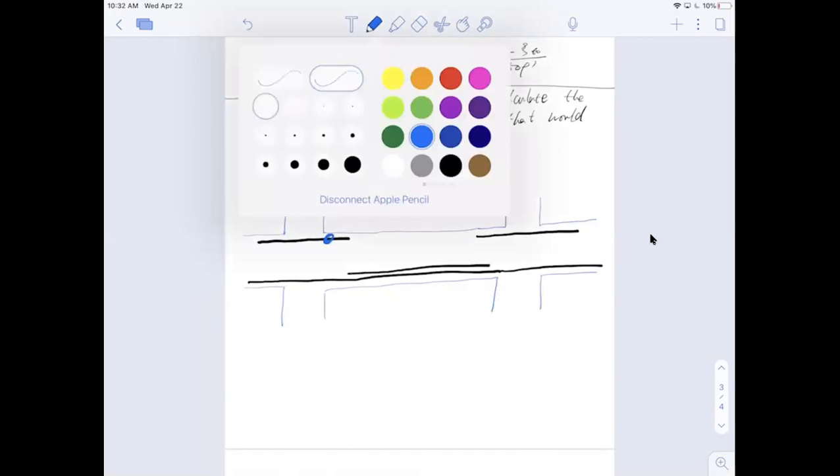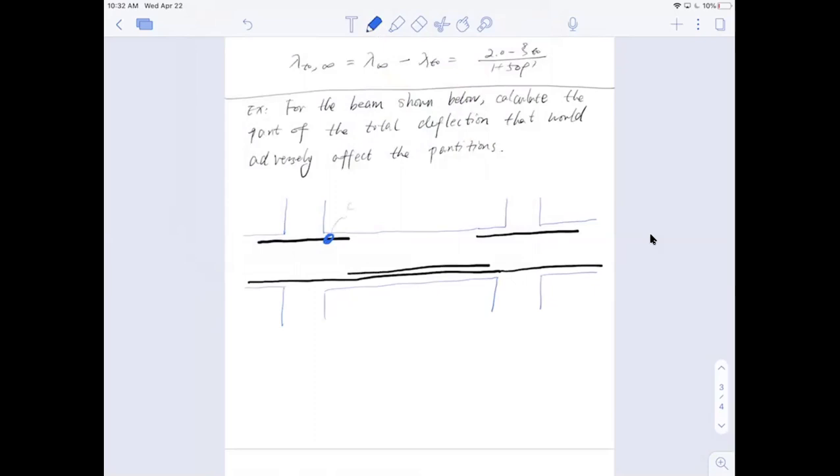Let me label them. It's too thin, so let me change this to a little bit thicker. Okay, this is 4 number 9 bars plus 1 number 11 bar. And this is also 4 number 9 bars plus 1 number 11 bar. At the bottom here I have 2 number 8 bars, of course the same 2 number 8 bars. Additionally, right here is 2 number 9 bars. And don't forget, the bottom here is 2 number 8 bars. So that's all the bar information I have.